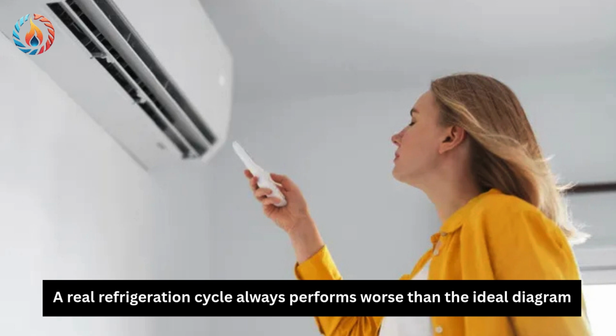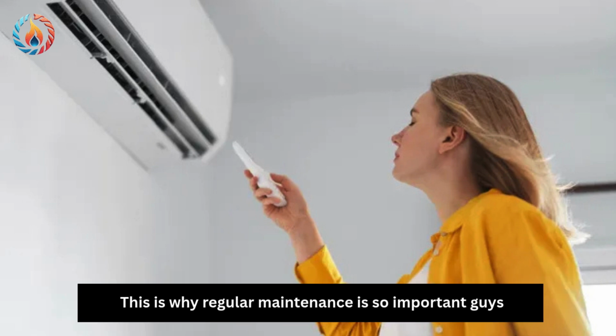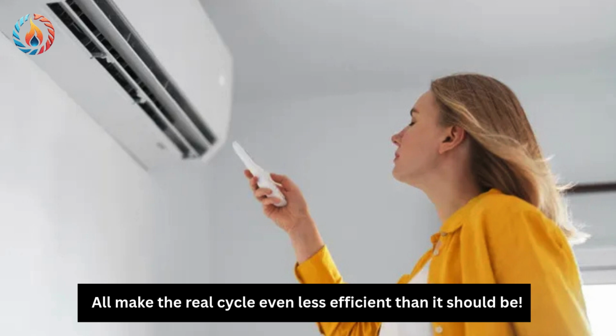A real refrigeration cycle always performs worse than the ideal diagram because of irreversibility, heat transfer limits, throttling losses, and pressure drops. This is why regular maintenance is so important, guys. Dirty coils, wrong refrigerant charge, leaky pipes all make the real cycle even less efficient than it should be.